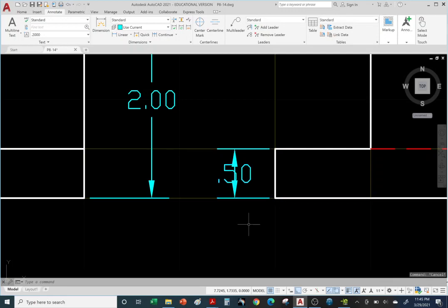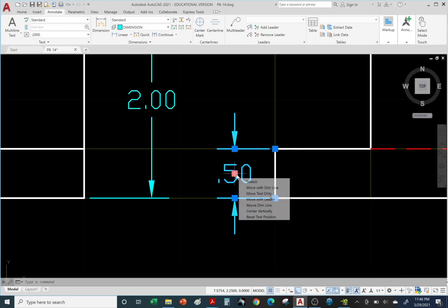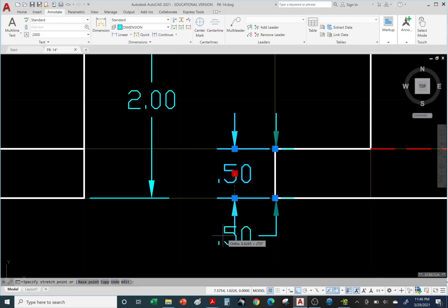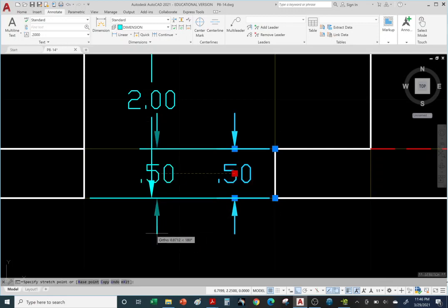it just doesn't look right, right? So you don't want to place a piece of furniture in your home facing in the wrong direction or crowding itself. So, hey, we need to do something to make it look nice. So we can just click on the dimension. Now we see the blue grips, hover over them and flip the arrow and flip the arrow. Okay, other options you have is if you still think it looks too crowded, you can leave it the way it is, or if you have the option to actually take the text out. So I'm going to hover over the grip over the text and I can take it outward, as you can see.